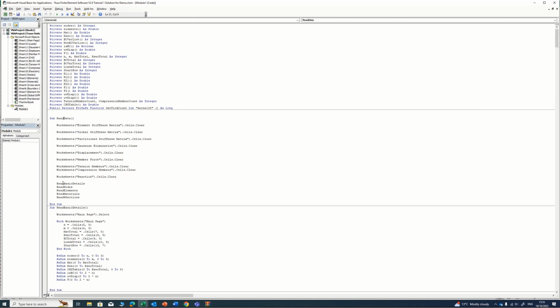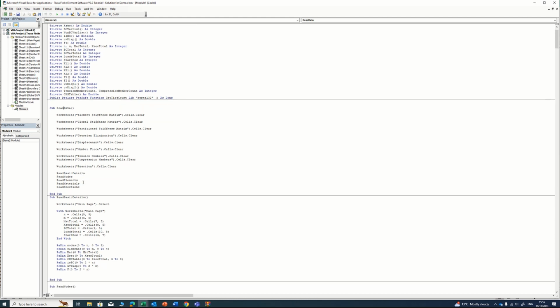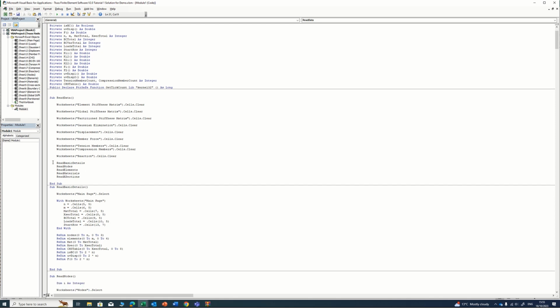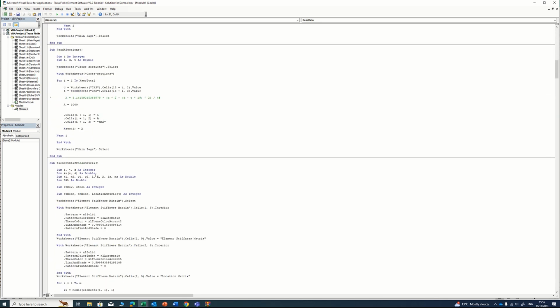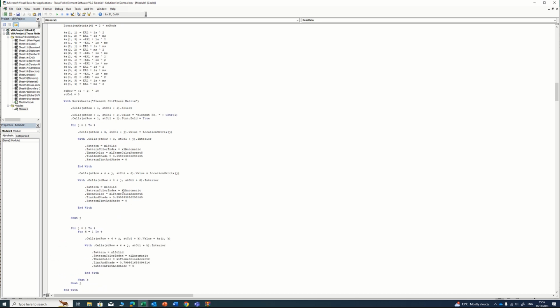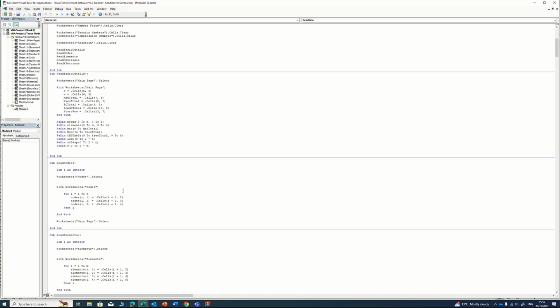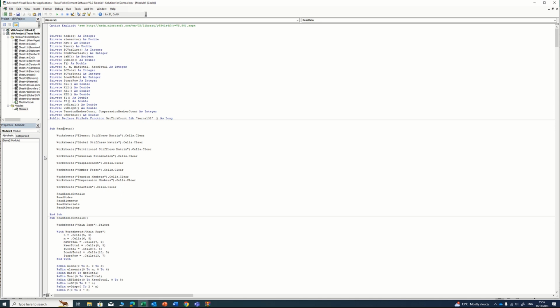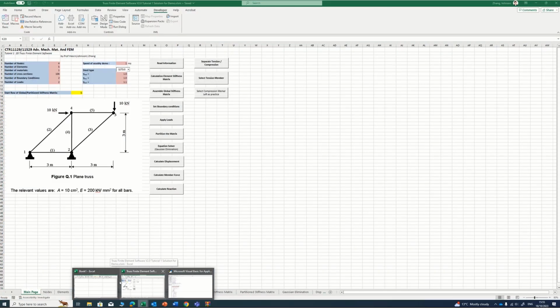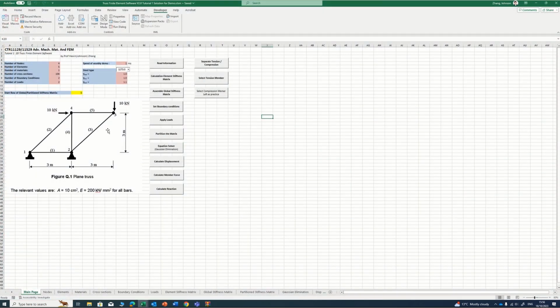After that, we're going to read the basic details, for example, the Read Basic Detail, and this line will call the next subroutine. That next subroutine will be run after you finish clearing out the tables, and so on and so forth. All this program is in here. So if you're interested in reading this, you can maybe set a breakpoint and then debug the program in here, like what I'm doing by clicking here. Then you can come back to the Excel file in here, click on one, and then run the debug information.